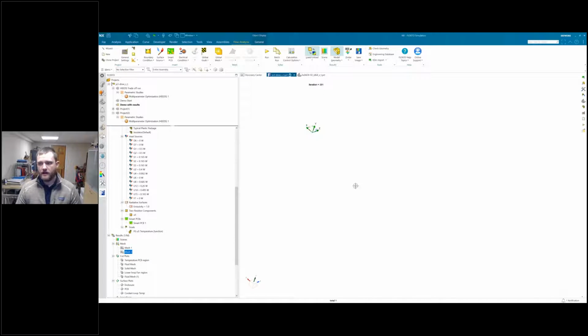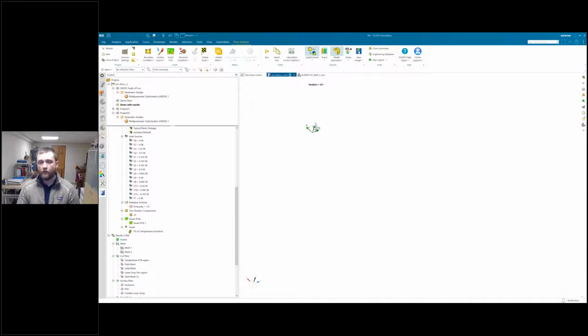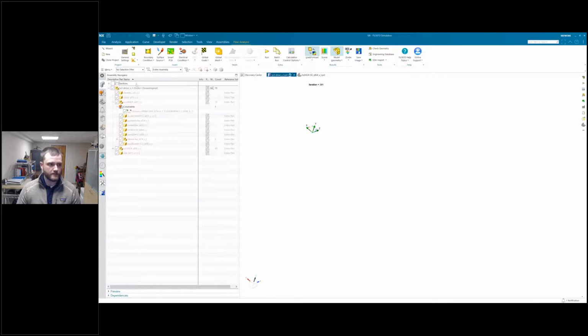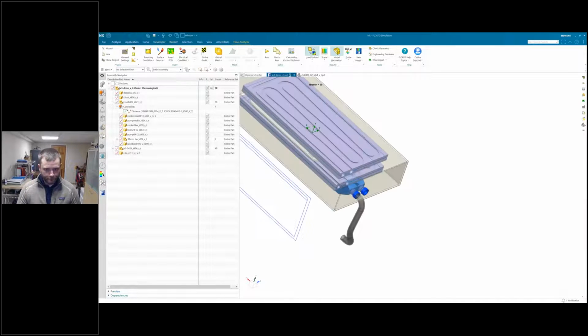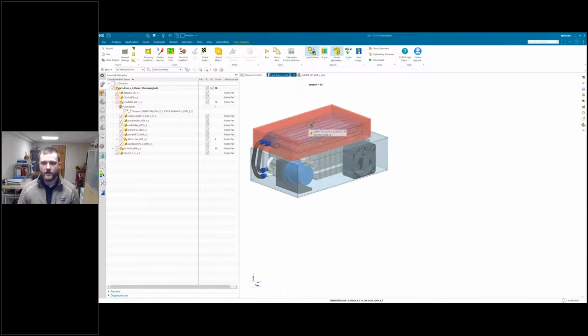We've shown the mesh. So let's say we were ready to run this solution. We can change our solution options here. We can change our goals, and goals are really how we monitor these solutions. So in a typical CFD analysis, you would always want to monitor relevant design variables, let's say pressure drop, heat transfer rate, the coolant temperature, the IC temperature, and we want to know that the solution has converged when, in this case, a steady state analysis, these values have stopped changing, they've come to a steady value. And that's really what we monitor in these solutions, and that's what the convergence algorithm looks at.